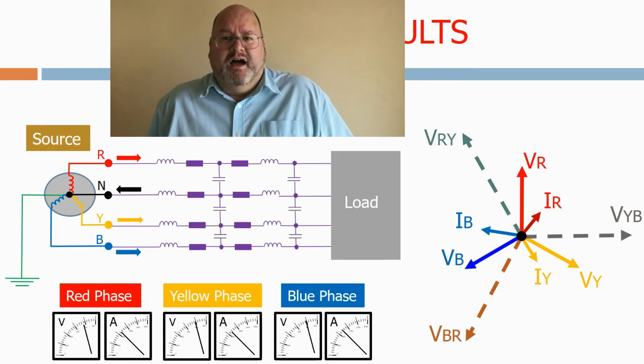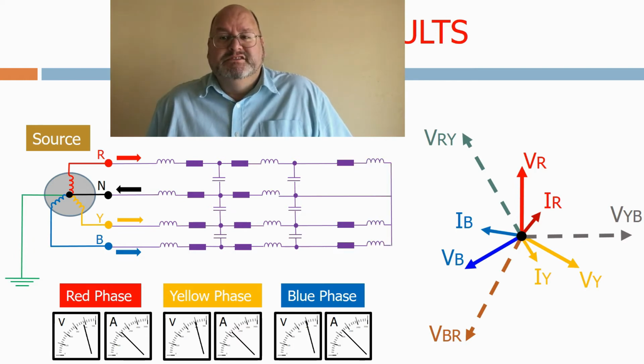The impedance of the line consists of resistance, inductance, and capacitance, which applies down the full length of the overhead line or cable. These will produce a total impedance for the line, which is called the characteristic impedance. The impedance of the load is normally inductive, but will obviously depend on the types of loads connected. For the transmission system, this load value will consist of thousands of individual impedances combined together.